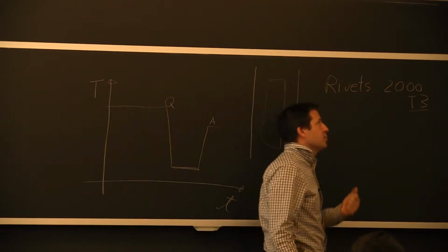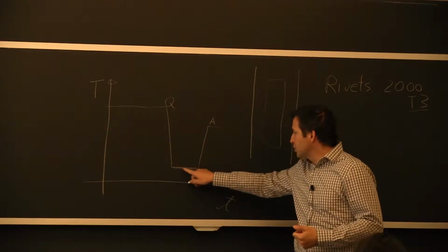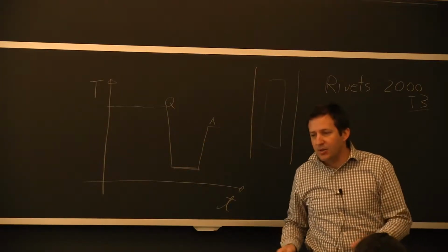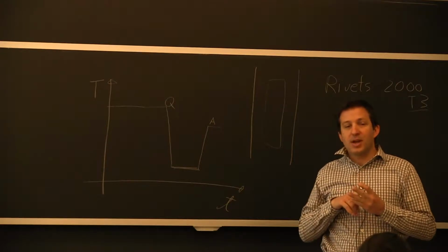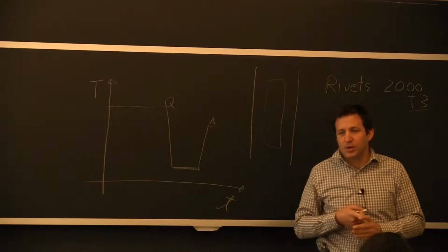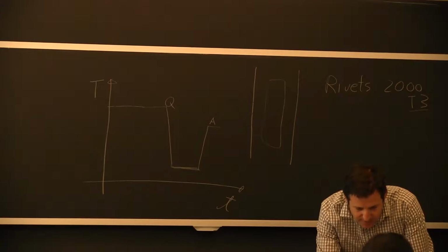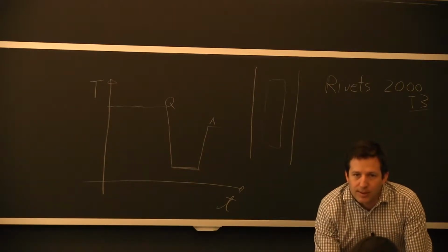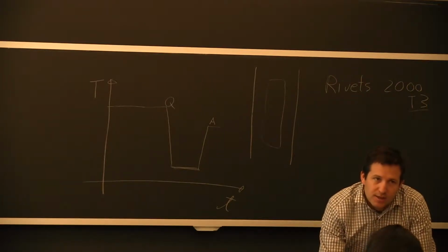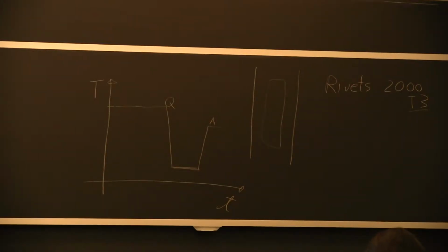What would probably help you a little bit here is there's a lot going on after you quench. When you start aging and you start forming the precipitates, there are, depending on the alloy series, approximately 4 different kinds of precipitates you can form. The first ones to form at low temperature are so small, and I'm showing some of them here. You're looking at less than 100 nanometers, little formations of a different composition in the aluminum alloy. So this scale here is 500 nanometers.